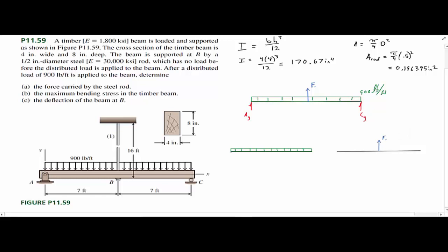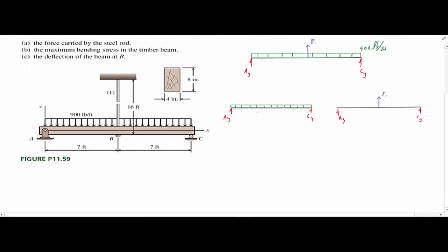And we can analyze each one of these based off of the formulas in the textbook, okay? And the formulas given, we can look for the maximum. We'll just use deflections, so the maximum deflections, and say for our distributive load, our deflection max is going to equal, based off of the formula in the book, 5QL to the fourth divided by 384 EI.